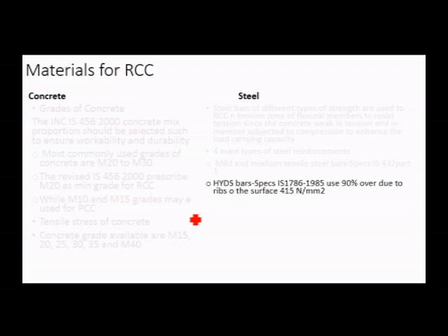These are used in over 90% of cases due to the ribs on the surface. The grade generally used is Fe 415.